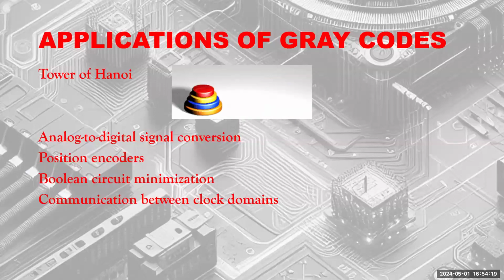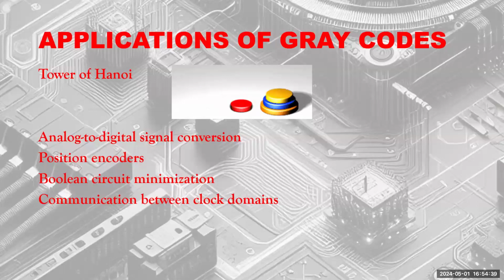There is some advantage to using such coding if it is a finite size state machine, not some very large state machine. And one of the more attractive state codings is called gray code state assignment, where you assign gray codes for the state movements. And even if there are different branches, you discover such gray codes that you can survive with one bit transition through such branch loops also. That is when you explore the bigger aspects of how to have two different future gray codes that still meet the gray code tenet. You will have to expand the gray code size to meet that multi-branch requirement.